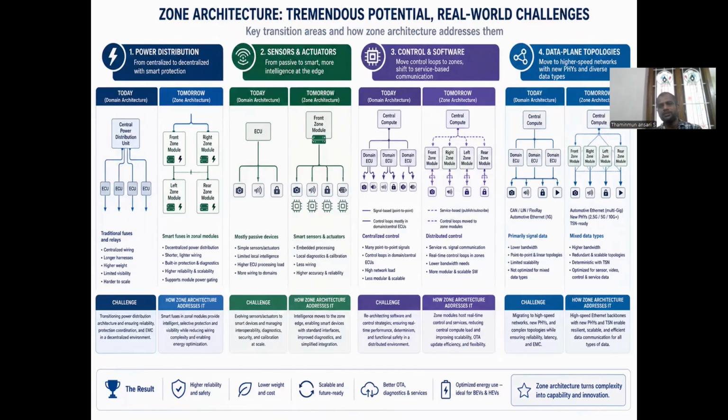When we turn off the ignition, they will shut down the clock signals applied to different peripherals of the ECU or controller, and they will put the controller in idleness so that it consumes current in the order of microamps or milliamps. Because the battery stays connected to the vehicle forever, 24/7. It doesn't mean that we turn off the battery when we turn off the ignition.